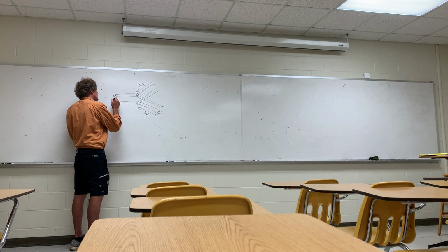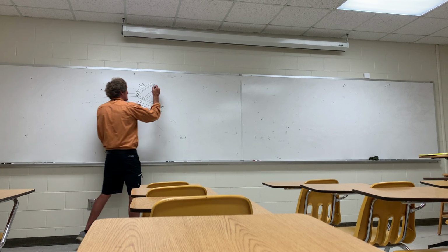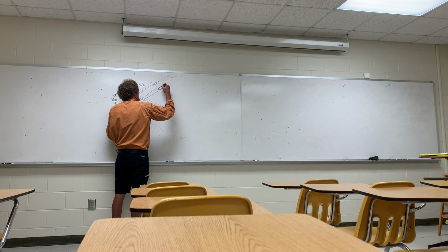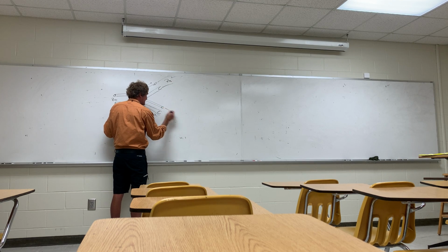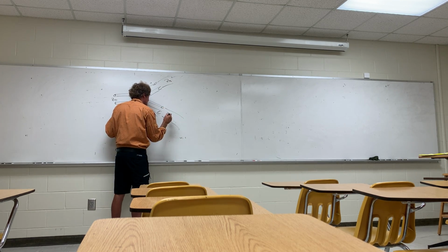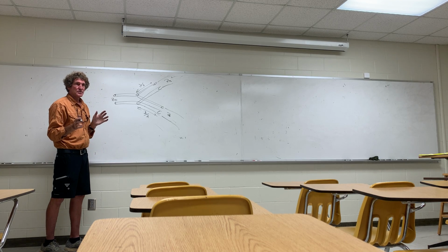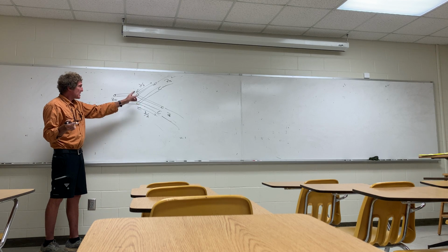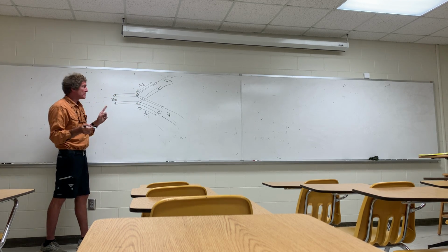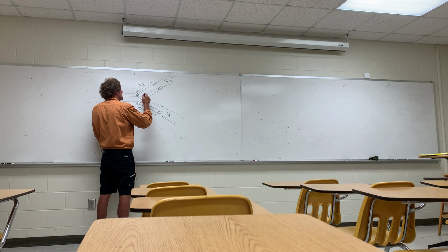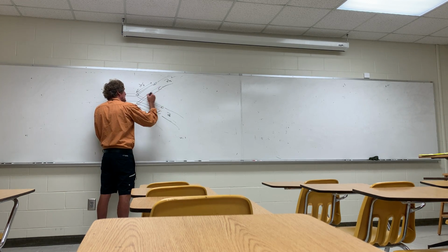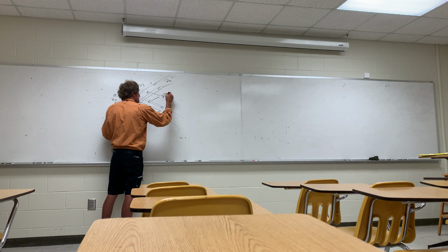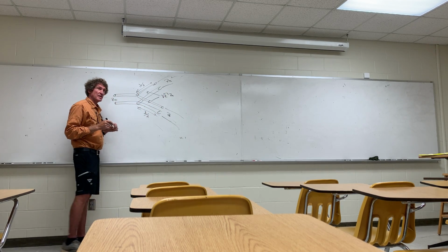Now follow me, this is going to have a characteristic impedance of Z0. Coming out this port, the characteristic impedance is Z0. Coming out this port, the characteristic impedance is Z0. Y'all follow me on this class? So all the ports have the same exact load, Z0. Each of these is a quarter wavelength long, but the impedance of this line right here and this line are both going to be square root of 2 times Z0. Y'all follow me on that?